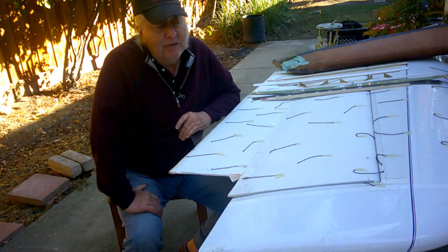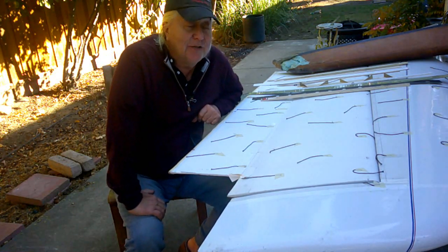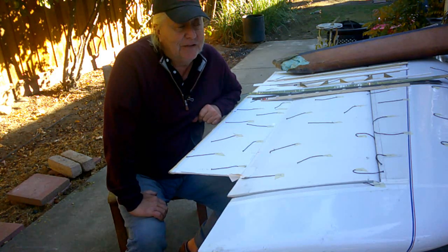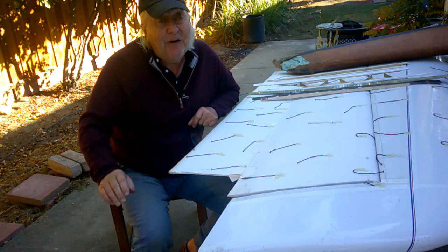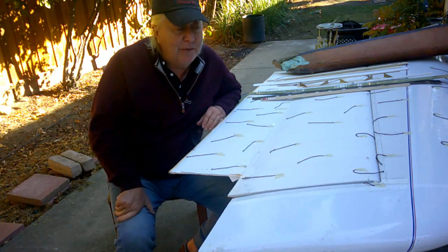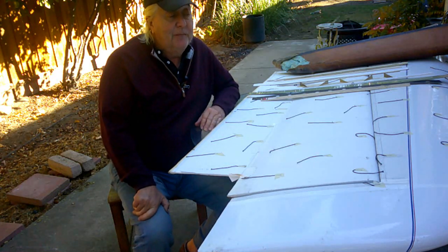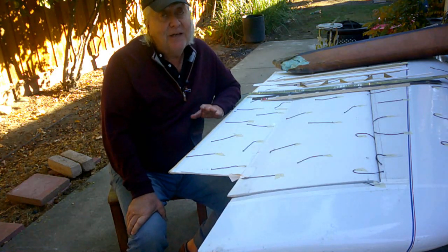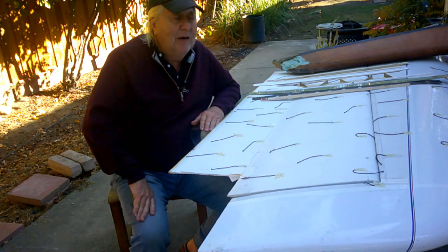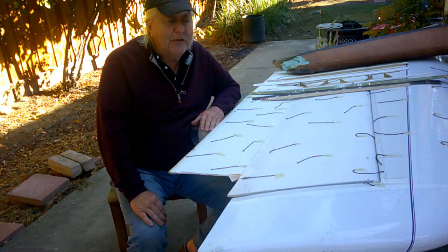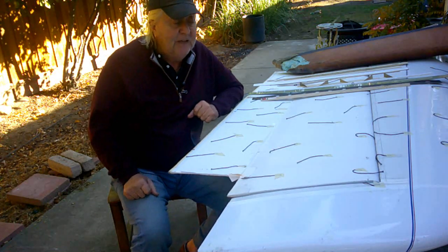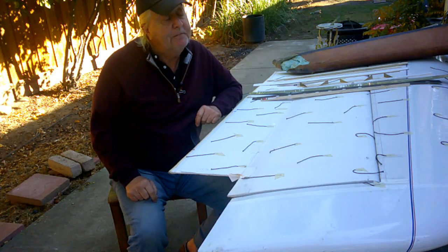And, you know, it really isn't in the size range of my original wing. My original wing was about 34, 35 inches out at the tip. At the very, very curved over tip, yeah, less, but at the last rib, right around 34 inches. And that was more like 500,000. Had a slightly lower stall speed, down around 18, 19 miles an hour, but still getting pretty close to right around the 500,000 range, in and out of it. But enough to make a difference.